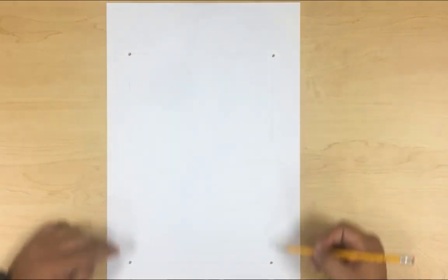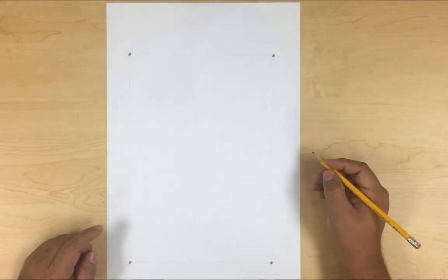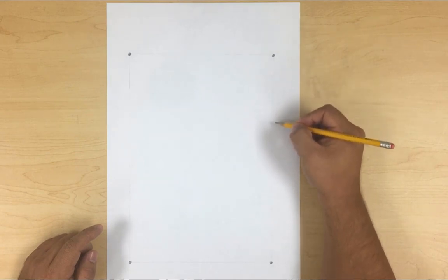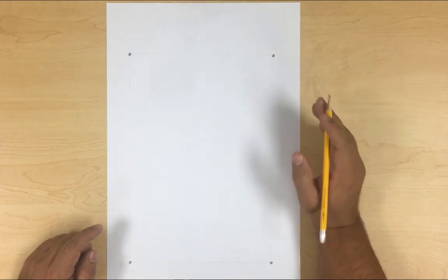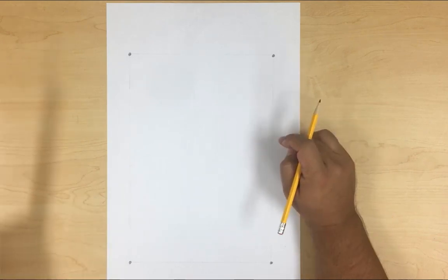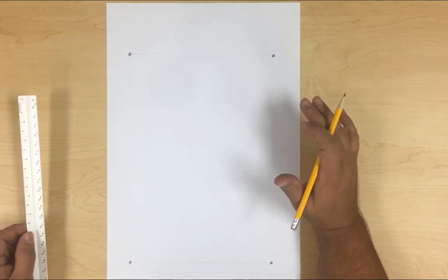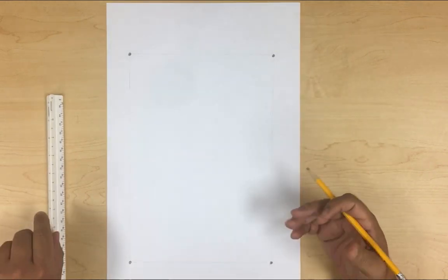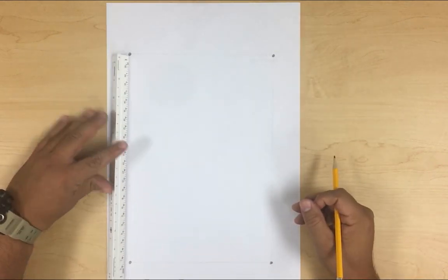Okay, and we're defining where the points are. So now we need to draw the actual lines or property lines. Those are going to be phantom lines, and those are going to be dark. The first thing you want to see on your site plan is where your lot is, and those lines have to be darker so they pop out at you.